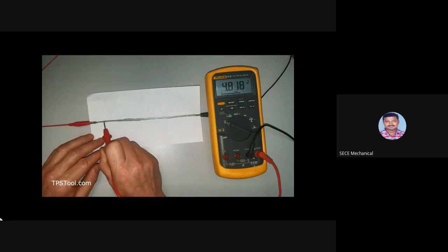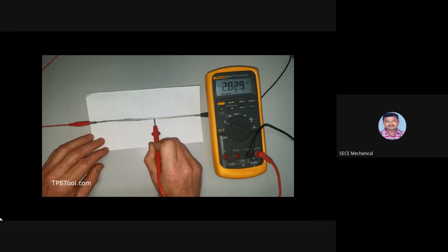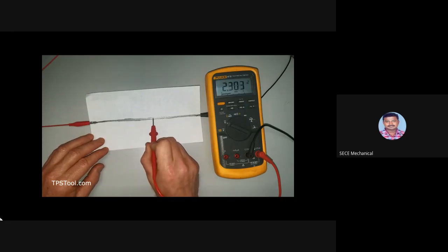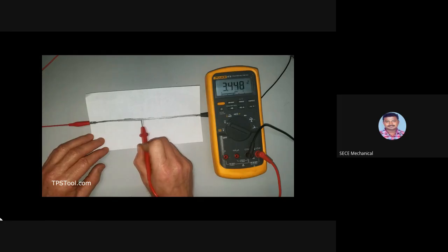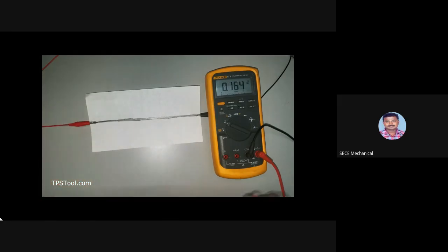So this is exactly how the throttle position sensor works. There's a mechanical wiper that moves up and down a piece of material that has current flowing through it, and the wiper is used to read the voltage at that location. That's how we convert a mechanical position to a voltage that the computer can read. So let's dive into the real thing and take a look at how it works.